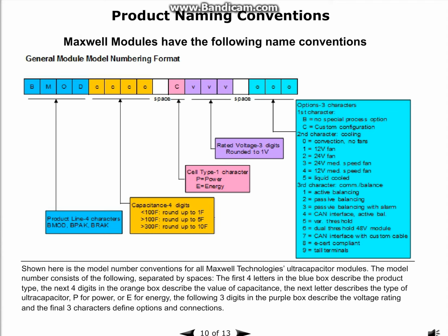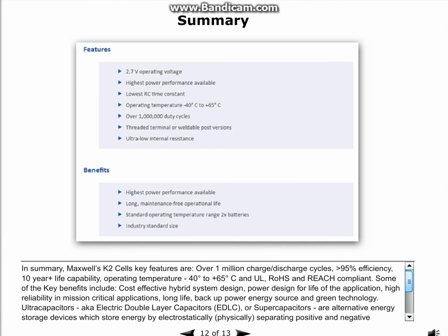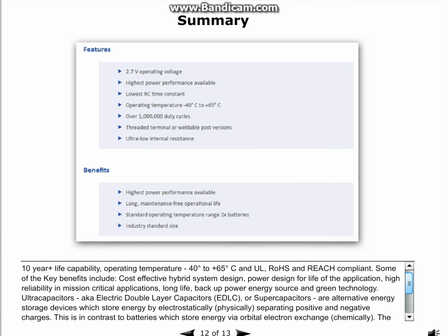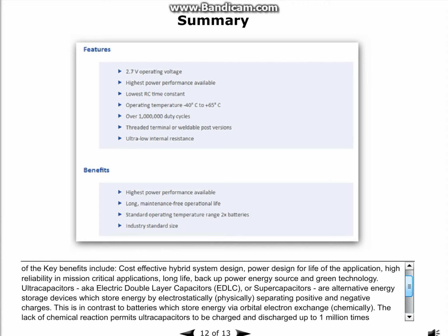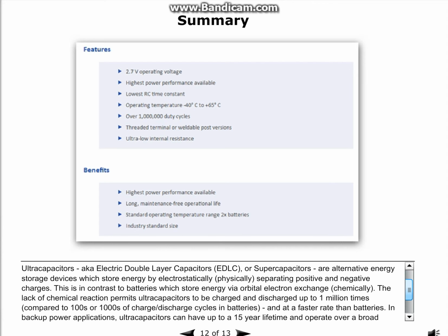For a systems design, it is important to take the end-of-life criteria into consideration for system performance over time. The end-of-life, EOL, is determined by a decrease in capacitance and an increase in ESR. End-of-life becomes a defined point, not an actual failure. Maxwell defines EOL when one of two things happens: a decrease in capacitance below 80% of rated value or an increase in ESR to...